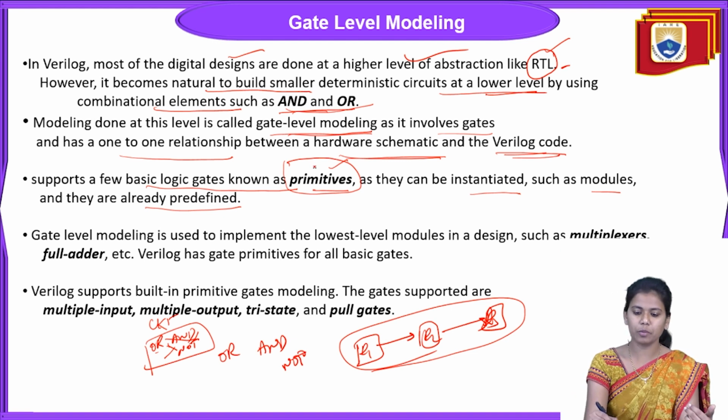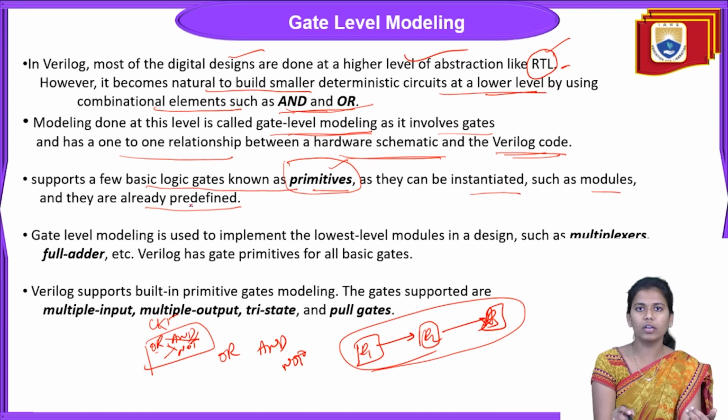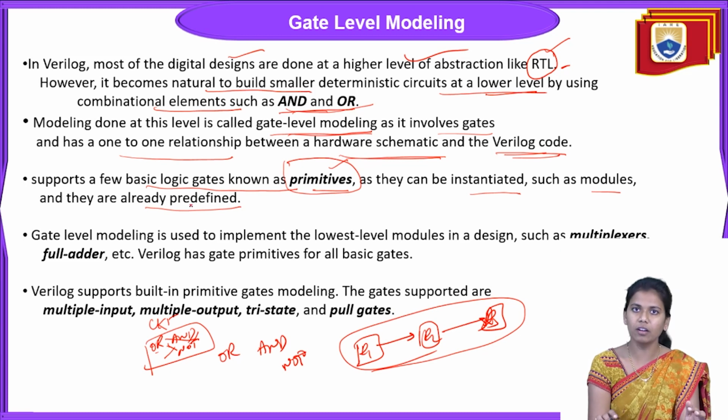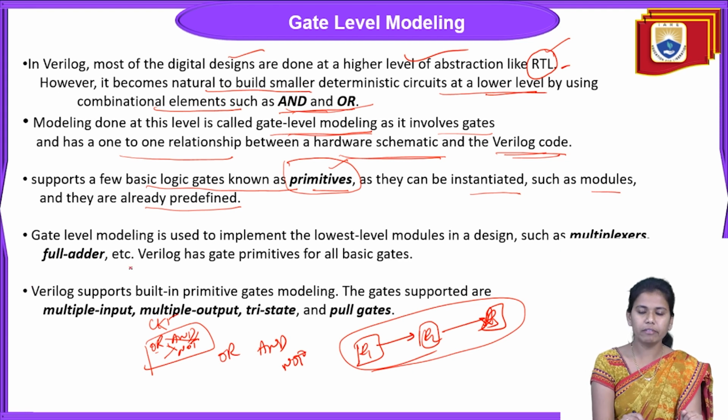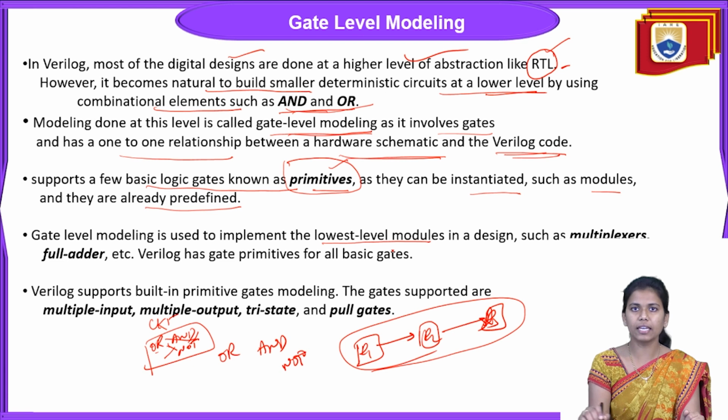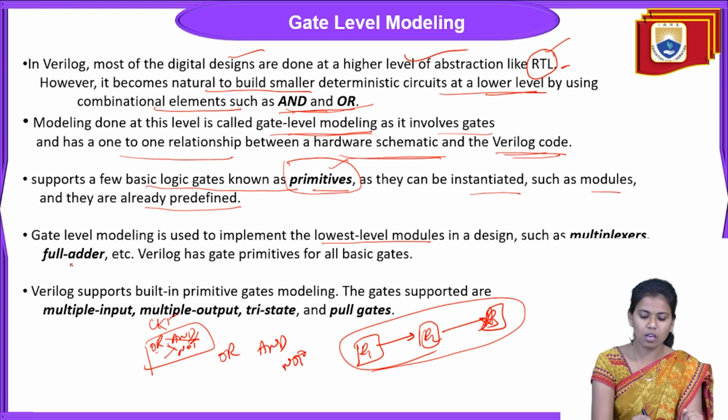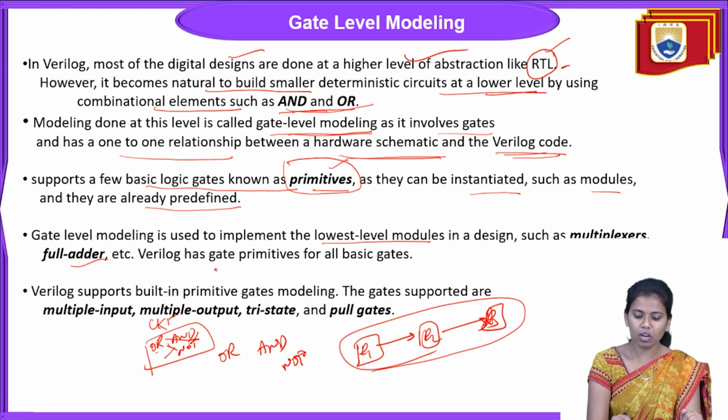All such things are nothing but the primitives. Already they are inbuilt in Verilog. Already they are predefined in Verilog. So gate level modeling is used to implement the lowest level modules in a design, such as multiplexers, full adders, etc. Verilog has gate primitives for all basic gates.